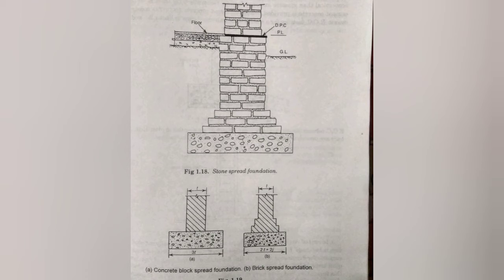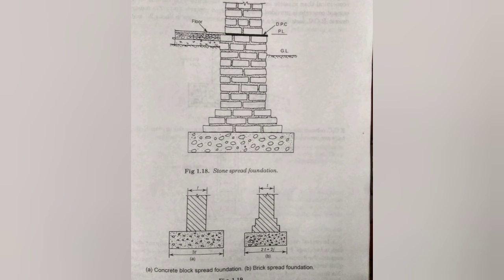In case of wall footing, they are: it provides a plain surface upon which footing masonry can be directly started. It rectifies the inequalities of excavation. It bridges over the soft patches in the soil below. It distributes the transmitted load over a large area. The concrete bed layer is kept 100 mm to 150 mm projecting beyond the bottommost course of the footing.